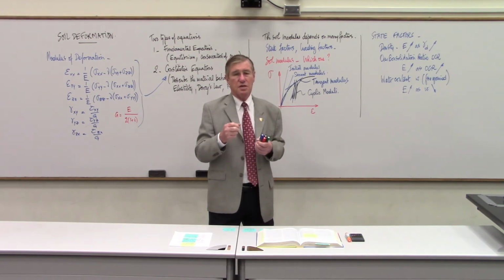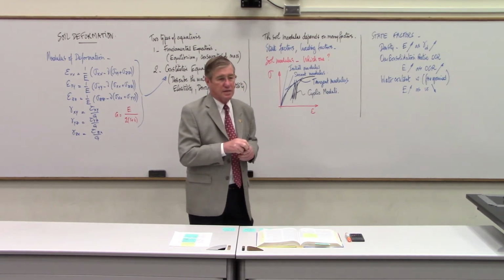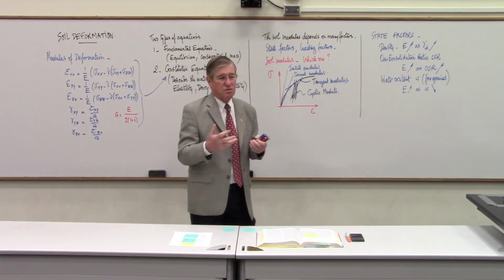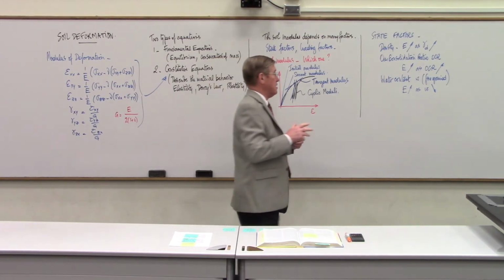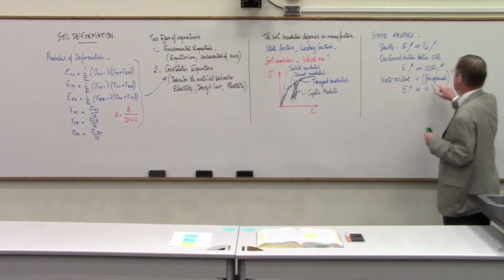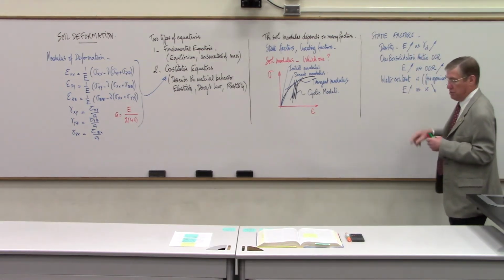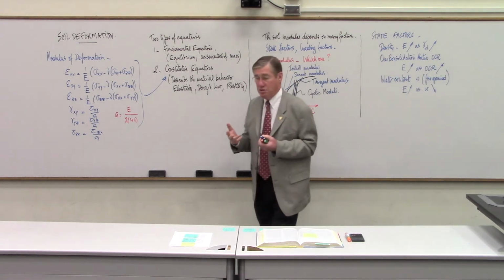Water has a tremendous amount of tension resistance, and so it's able to really attract particles. So that's why when the water content goes down, particularly in fine-grained soil, the modulus will go high. And as an example of application, compaction.